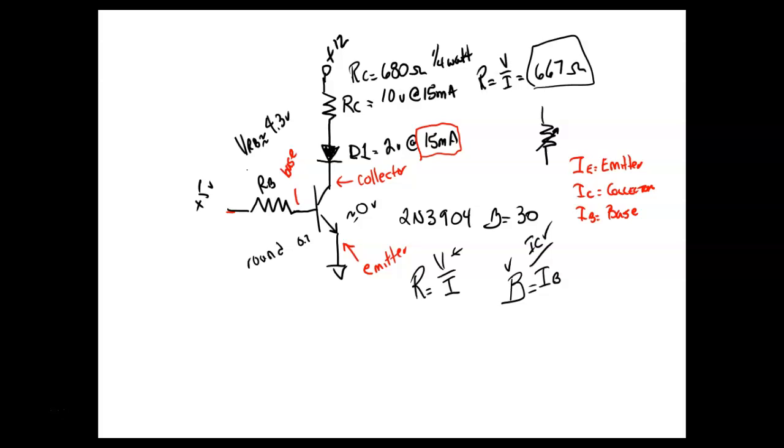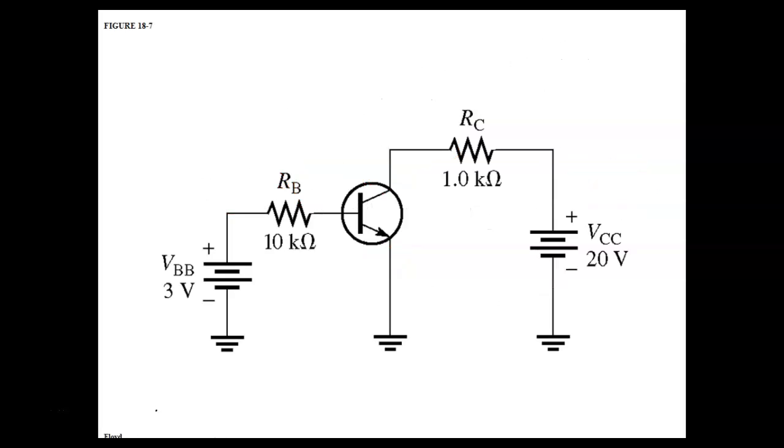So we use the same common. We have two power supplies. If I was to draw the entire circuit, this is what I would come up with, except this right here would be 5 volts and this right here would be 12 volts. So this is the circuit that we have wired up, and of course, we got the LED right in here. Currently we don't know this one, and currently we calculated this to be 660 ohms. Okay, so this is the circuit I got right here. I've got two power sources here.